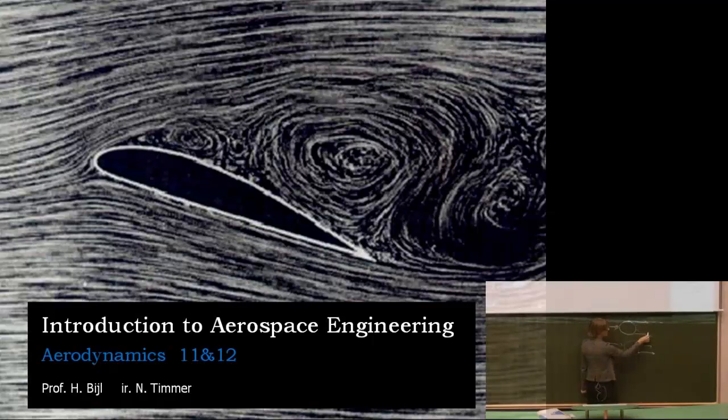What will happen inside here, of course, there is actually some flow, and it will be entrained here. And quite often you get then vortices like this. So they are entrained here and go back here and then like this. And that is why, because somebody asked, okay, if I have a vacuum here, of course it would collapse again. But that is not true, because this fills sort of with larger vortices, but there's not actually a streamline from here to here, so you cannot really apply Bernoulli. But you will remain lower pressure behind. So a larger pressure difference over this case than over this case, right? So a larger force, drag force, pressure drag.